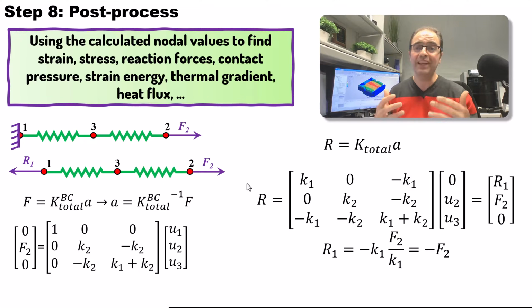Even in the most complicated models, finding the reaction force and making sure that the reaction forces on the boundaries are going to balance the external forces that are being applied to the structure is actually one of the validation methods that many engineers use for these models.